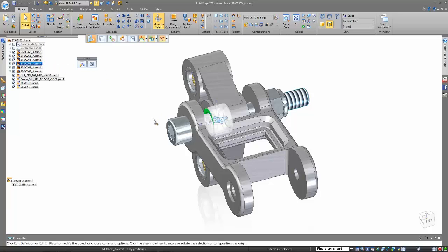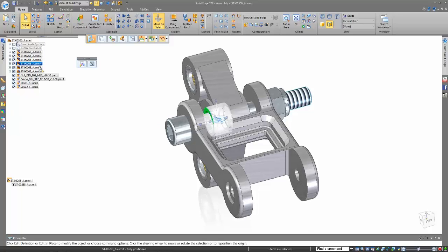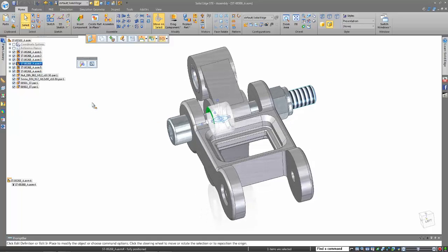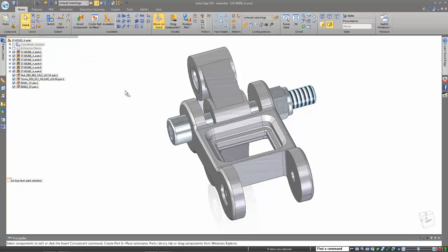Without doing anything in terms of assembly constraints or adding anything to the parts themselves, I can select individual assemblies, or I can also select individual faces of multiple components. Up here in your select application, there's also face priority, or I can get to that with a Control-Spacebar selection, and you'll see that my icon changes next to my cursor.